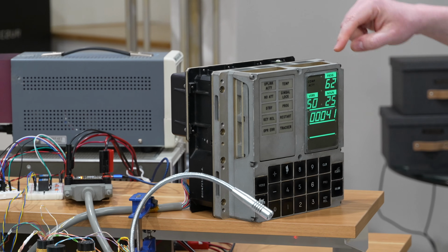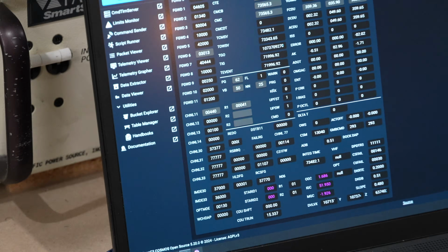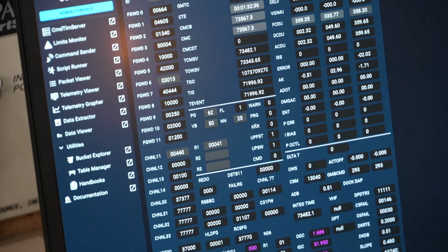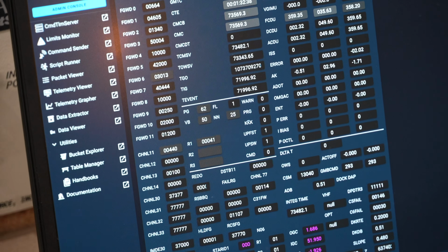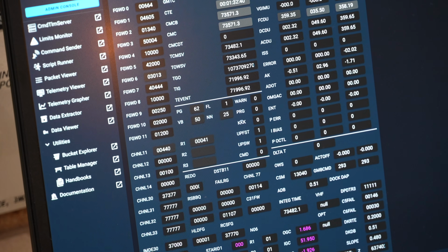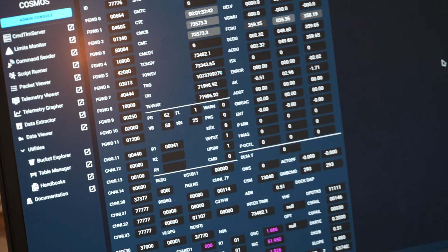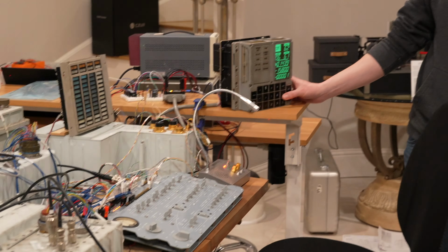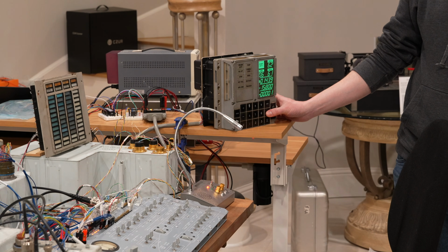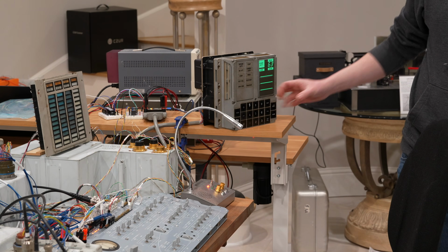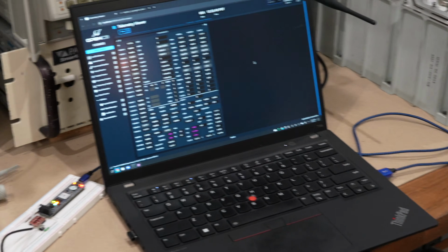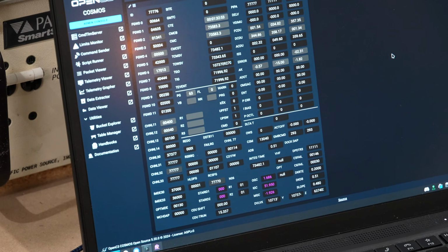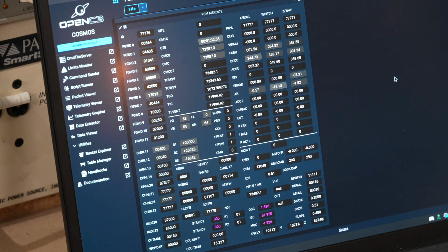So we just transitioned to program 62. This 5025 is asking us to perform command module, service module separation. Yeah, I see it. I see 5025, register 1 is 041. Yeah. So I'm going to proceed and say that we separated from the service module. Keep going through screens here. Now we're running P63, which is going to actually start looking for 0.05 Gs to be registered on the accelerometers.